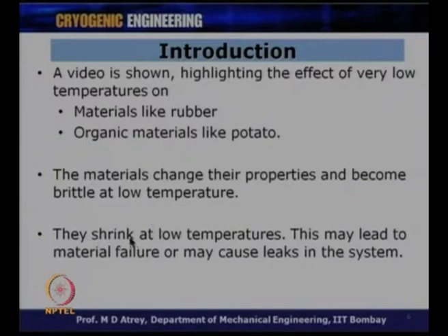If I do not take that aspect into account in design, it will lead to material failure, because as soon as the shrinkage happens, the failure will happen, or it can cause a leak also. Therefore, these are important design aspects related to safety, because with leaks, high pressure gas can come out, or the material can completely break down and it can cause some accident also. So, material property related safety aspects normally should be taken into account at the design level itself.